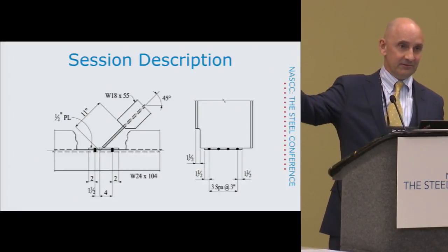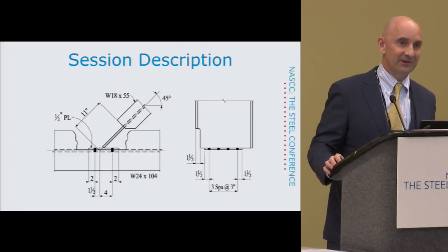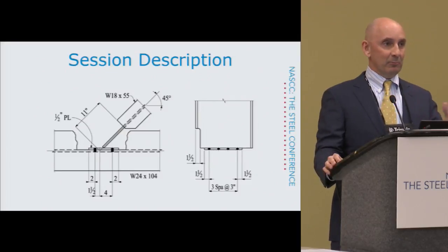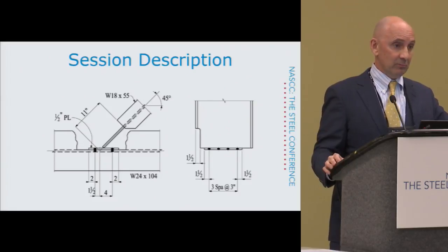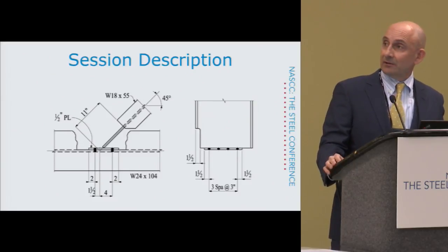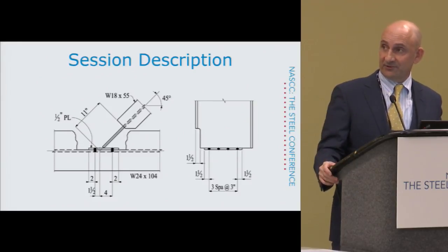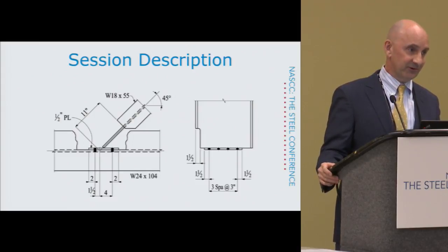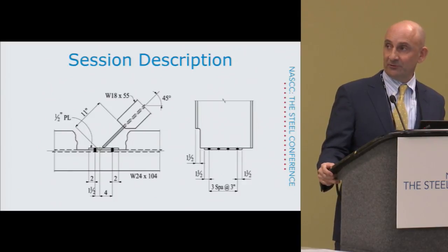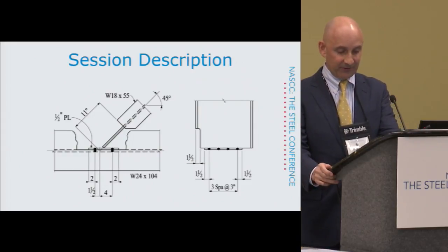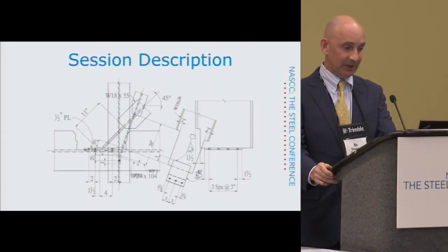This one and the next slide are both from a 2005 presentation I did, and they're both based on actual projects I was working on in the previous years. But I actually did another one just real similar to this, a bent support structure, in the last month or two. So you've got pretty big loads on those, so you end up with end plate type connections like that, rather than a single-sided, maybe a bent plate connection.